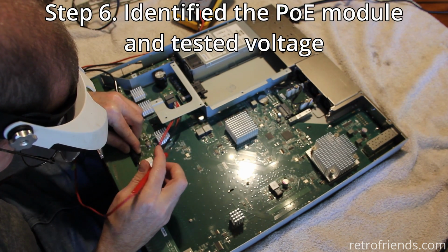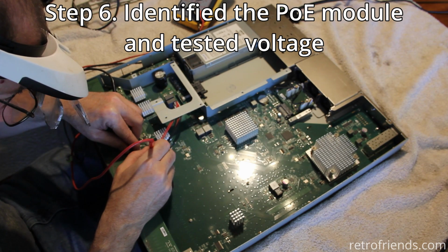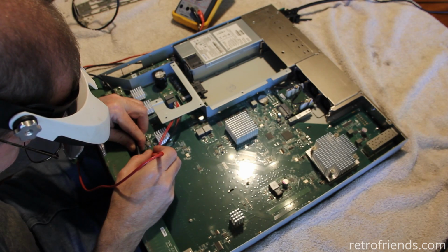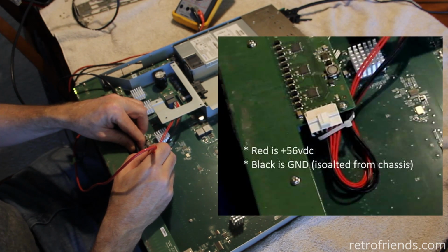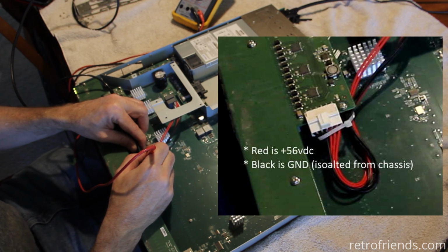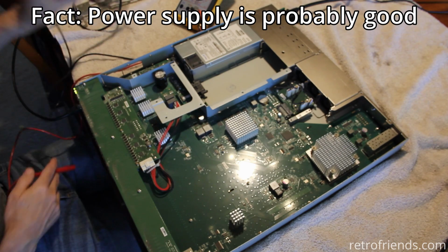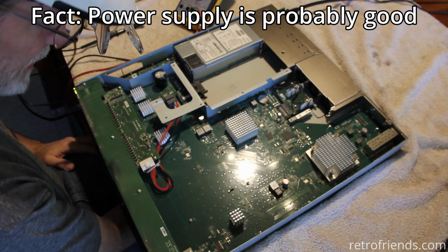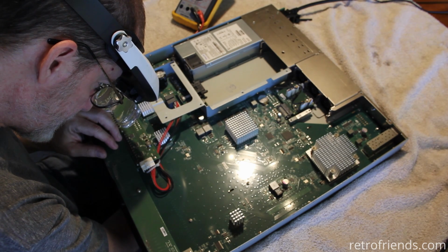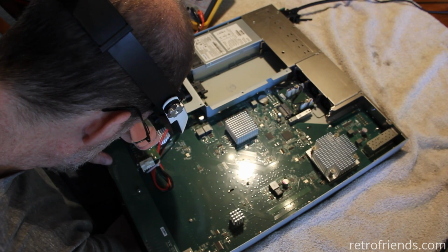I should try to plug in directly between these. Yeah, okay, there we go. 56 volts. See, that's what you would expect. 56 volts, okay. So 56 volts coming into this board. We're probably talking about a failed component. Ooh. And I think I might have found it.